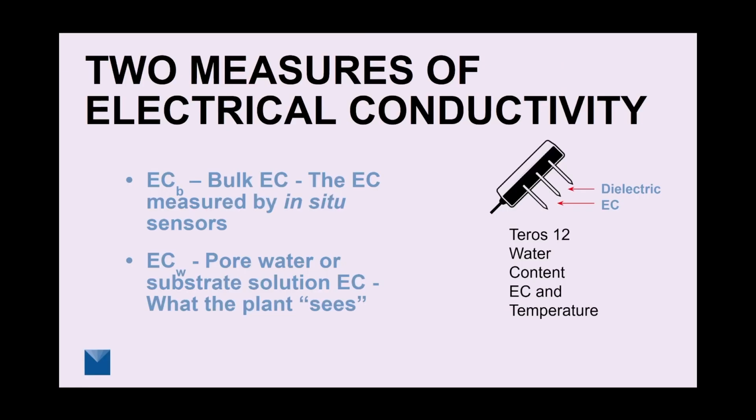Okay, the Teros 12 has 3 prongs on it. We measure the dielectric of the substrate solution between the center prong and the end prong, and we measure the electrical conductivity of the solution between the center prong and the base prong.